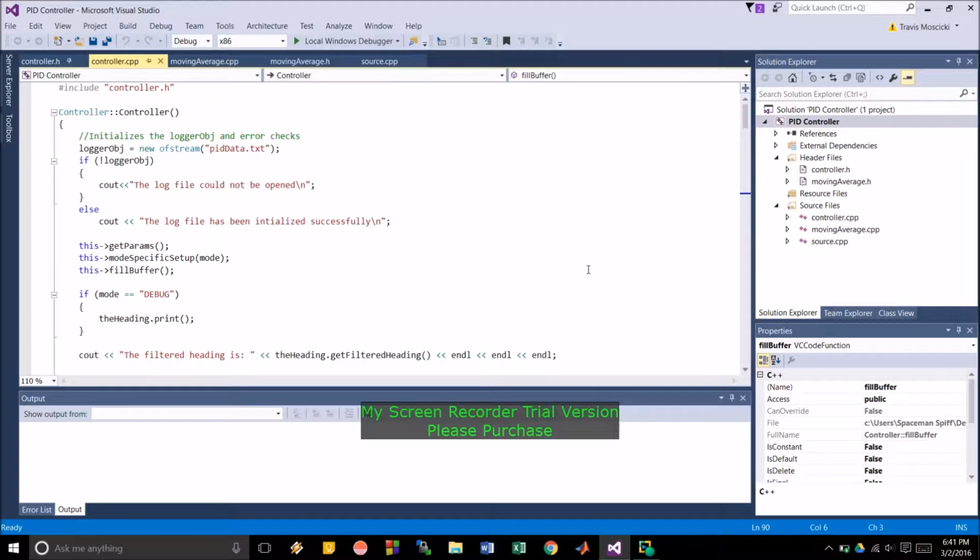So now you can do things like Fourier transforms and other frequency domain assessments on this function, where really, let's say that now instead of a sine wave, we have a square wave. Kind of the idealized case. Well, when you do your Fourier transform, this is going to have an infinite number of frequencies internally.